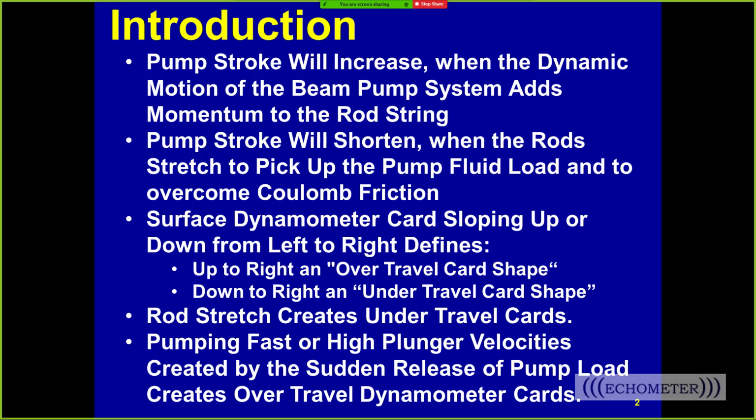Now, the acceleration force on the upstroke typically is required to pick up the fluid load at the surface, so there's a much higher force applied at the surface to apply the fluid load force at the pump, and that creates the peak load. Then when we release the pump load on the downstroke, that also is an acceleration force that we create on the downstroke that creates the minimum load.